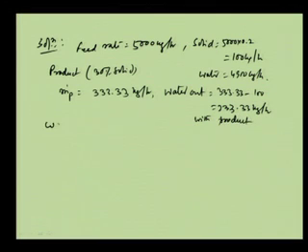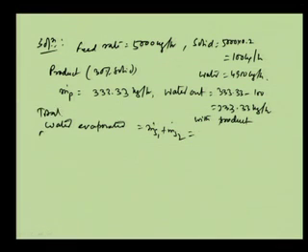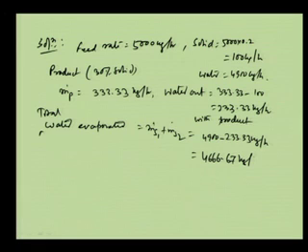So, water evaporated is equal to m dot S1 plus m dot S2, coming from the two effects. This is the total water evaporated and that will be equal to 4900 minus 233.33 kg per hour, and this becomes 4666.67 kg per hour. So, this is equation 1.